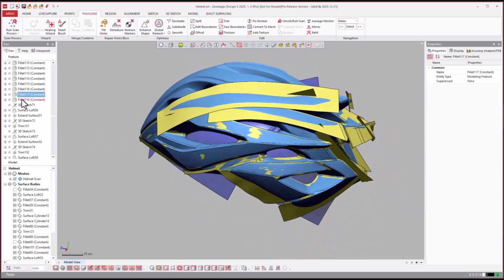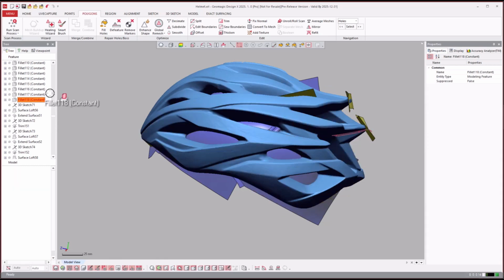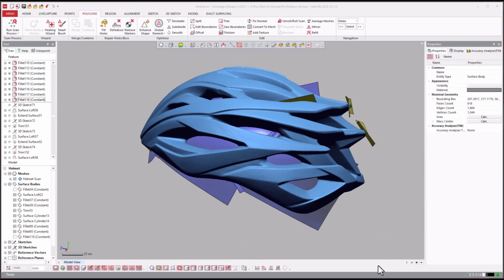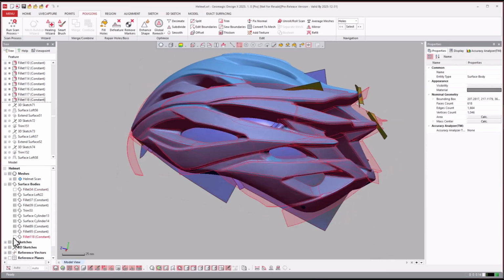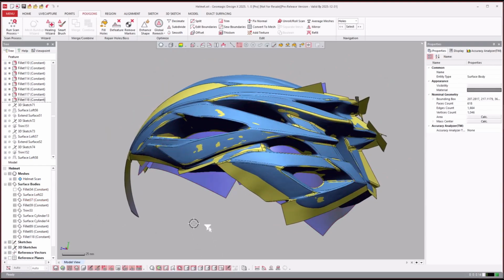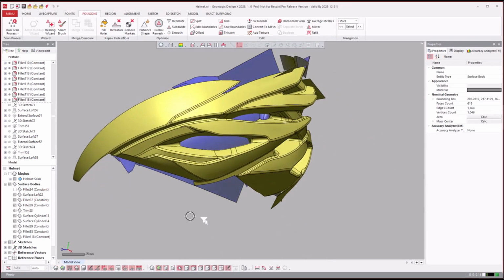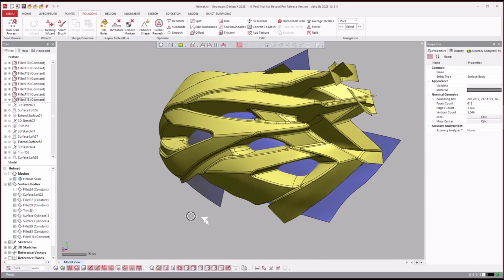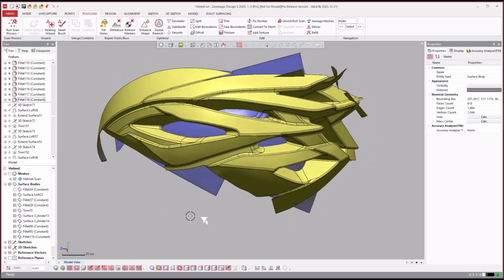If I see things in the history tree that I will utilize. Whenever, again, you see fillets back to back to back, it looks like they're blending something together and trimming something into the main piece. So that's usually a good sign of somewhere to jump in the history tree. So now, just turn that on, turn this off. Look at all that we got so far, all trimmed together, quite nice.